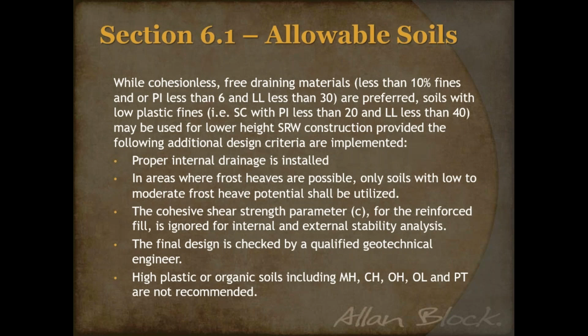But then other things to consider, frost. In the northern climate, especially where our corporate headquarters is in Minneapolis, Minnesota, our frost depth can be 5.5 feet deep. And I'm not so much worried about heaving up and down as opposed to maybe some bulging where you've got frost susceptible soils right behind the wall. That's another reason why we use that clean stone, at least 12 inches there, to try to prevent any of that swell or that heaving. And there's times when we've got to make sure that's done properly too. So if you've got real frost susceptible soils, you might have to increase the amount of rock you have there too.